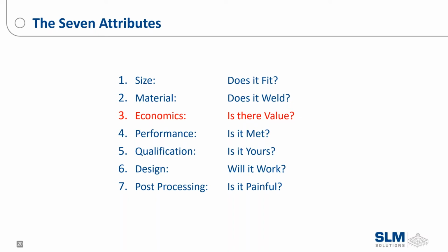Now, for about 80 to 90% of the jobs, these are the materials we use every day in the lab, which I run. That being said, there's always new materials being developed. We have an open system, so that allows us to take any material that is developed, and as long as it meets specs for flowability and powder size, we can run it through the system, create a set of parameters for it, and then continue on and develop a case for that new material.